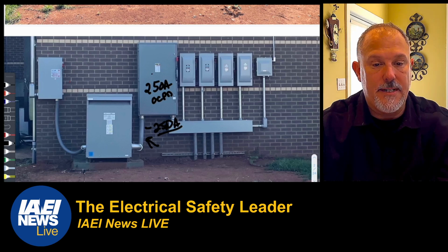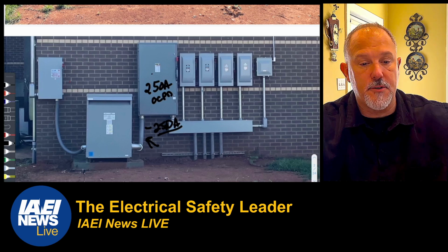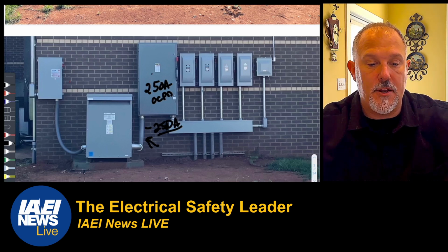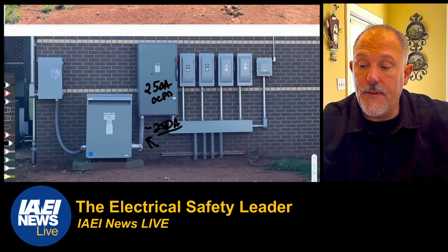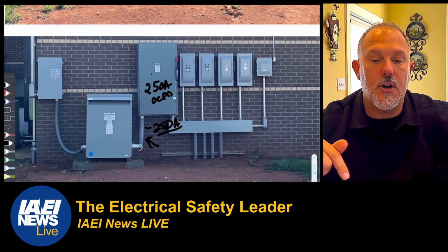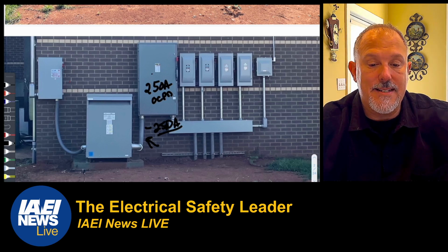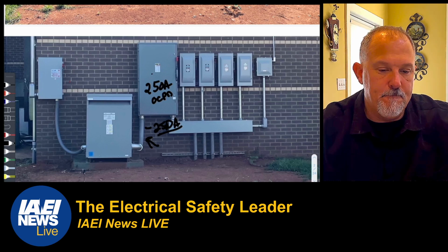Now, the second criteria, and it has all of the following. So you've got to meet number one, you've got to meet number two. The secondary conductors do not extend beyond the switchboard, switchgear, panel board, disconnecting means, or control devices that they supply. So that secondary conductor can't go beyond that secondary equipment. And the secondary conductors are enclosed in a raceway, which these are, which shall extend from the transformer to the enclosure of the enclosed switchboard, switchgear, panel board, etc.